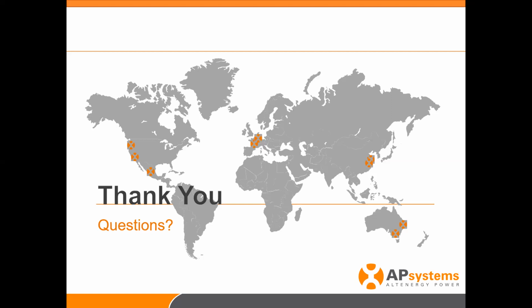Another one here. What is the maximum input for each MPPT on the YC1000? Good question. So just a reminder, the YC1000 is a single MPPT. So it really depends on what you want to put into it. What I think we need to do is look at the maximum AC output, which is 1130 AC watts. And like I suggested, stack the deck in your favor by making sure that the modules you choose to put on there exceed that AC output. Not by a ton. I mean, you don't want clipping.